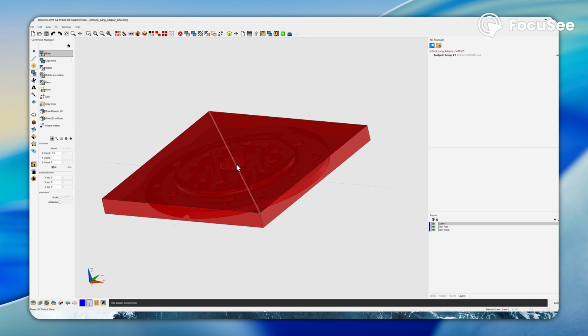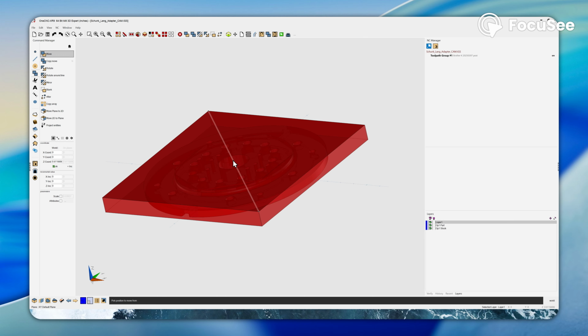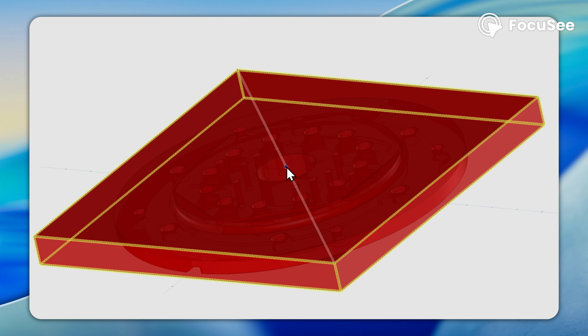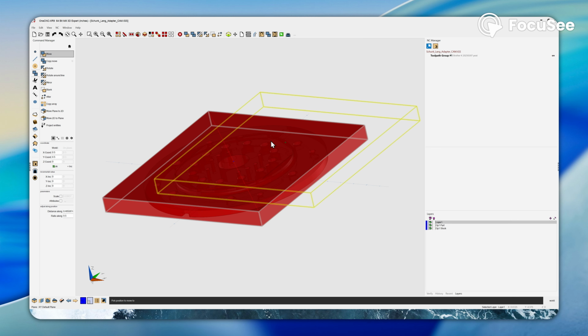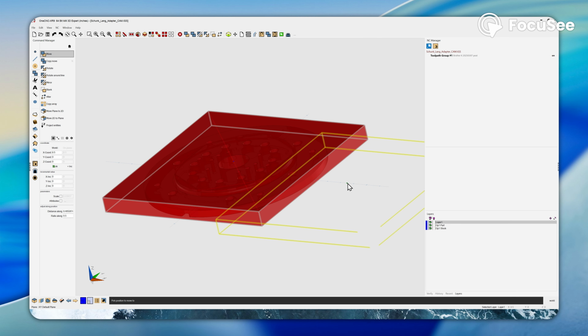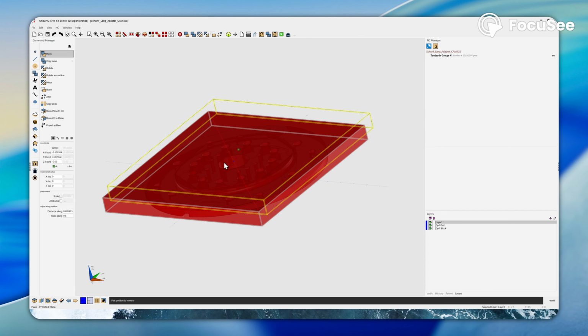And now if we hover, you can see that I can pick up the center of that line. And if you look over here, while I'm hovering on that center, you can see that the point that I'm currently at is x0, y0, z plus 0.8 and some change. So let's just click that. Now you can see that the whole part's moving around with my cursor. I could go and click on some other feature and I could attach all of this stuff there.